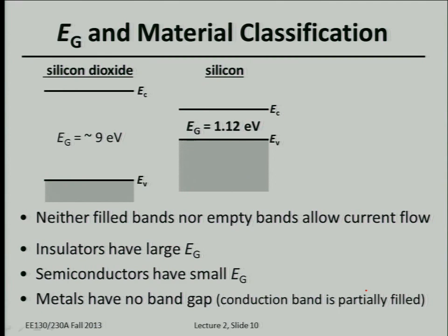Maybe next lecture we'll derive an equation for the intrinsic carrier concentration. But if the energy between a valence band and conduction band is so large, it's highly unlikely that, due to just random thermal motion, an electron will gain enough energy to escape a covalent bond. So what does this band gap energy represent in the bond model? Right, it's the energy needed to escape a covalent bond, exactly.